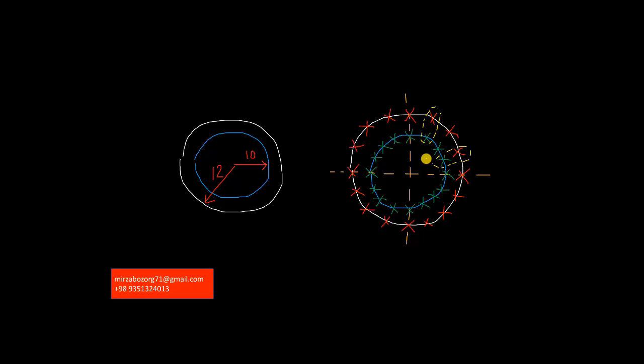Then she didn't face any convergence issue, but the contact results were not reliable. And we finally found that even for explicit analysis, this mesh design must be used. This is very important.